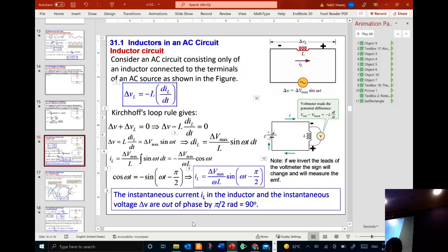Okay? Clear? So in some books they use one convention, in some other books they use another convention. So let's stick with the Serway convention, which is how we're measuring. So when we measure the voltage across the EMF, we bring this black here and the red here. So we measure, for example, the voltage here. Then we move here and we measure the voltage here.